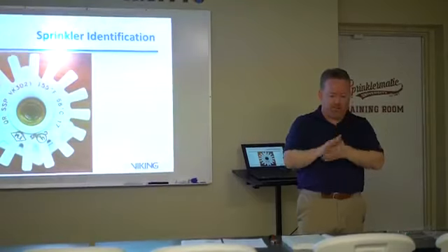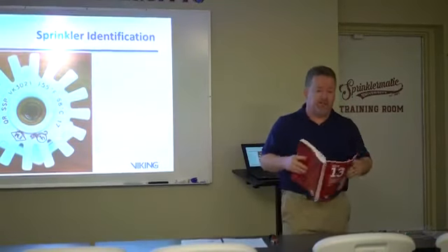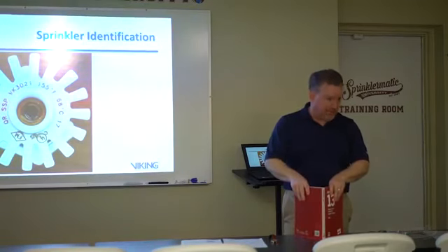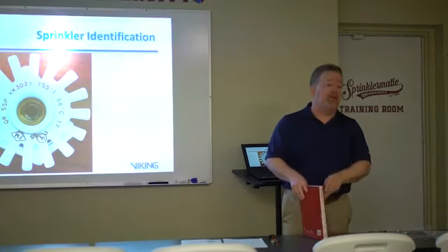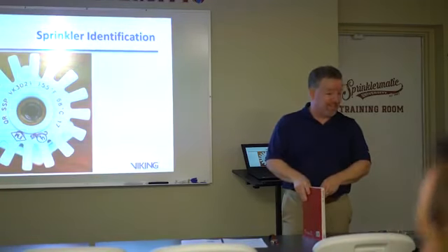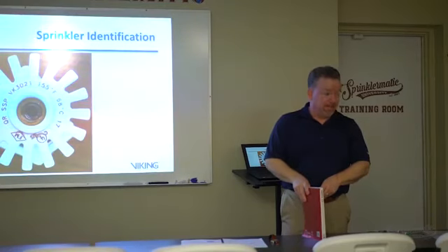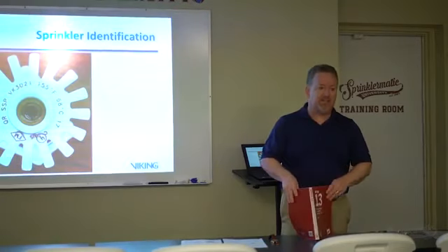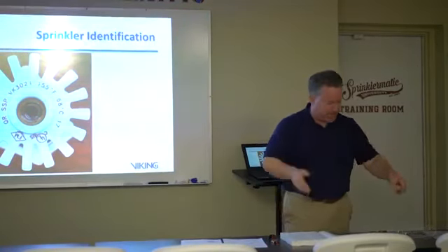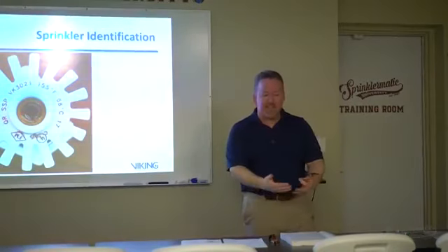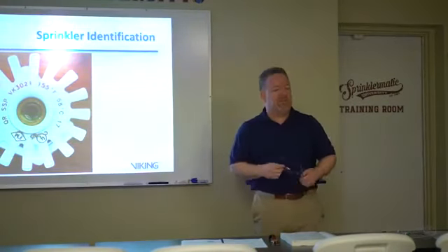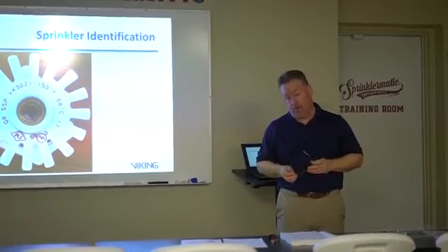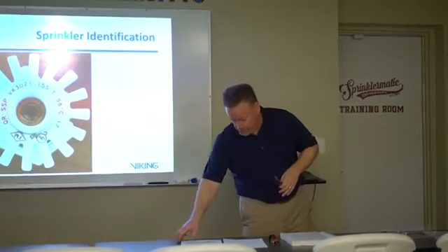If you've got a sprinkler system that is being designed in a Factory Mutual property, they will require you to follow the Factory Mutual guidelines for the installation of the sprinkler system, okay? They have their own written guidelines, and that becomes a pretty big deal when you start looking at how they protect storage and how they permit sprinklers to be designed. So they're not exactly the same as NFPA 13, they're pretty close, but there may be some additional requirements or some differences in what Factory Mutual would require you to do.